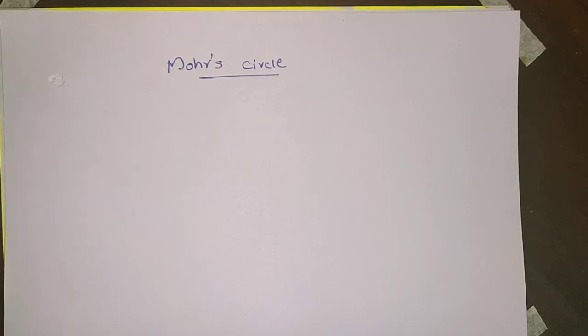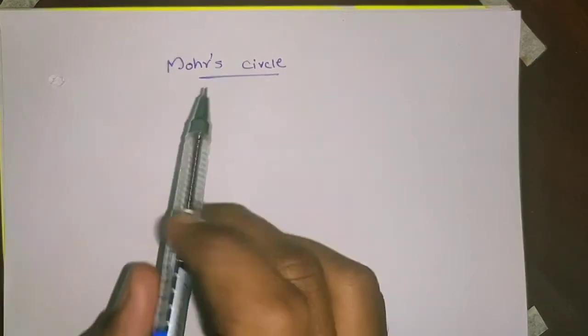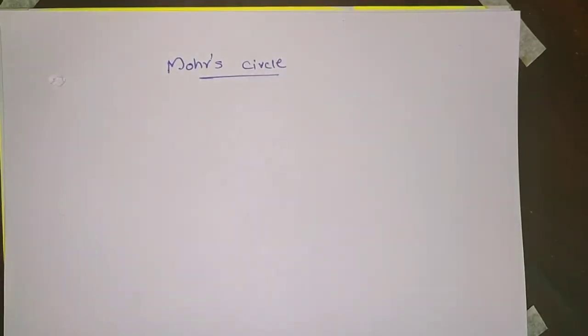reference planes. So that is the theoretical approach, and the transformation of stress components can also be calculated using a graphical method. Instead of using those 8 formulas for the calculation, here we use the graphical method, known as Mohr's Circle. The stress components on any inclined plane can be easily found with the help of this geometrical construction called Mohr's Circle.